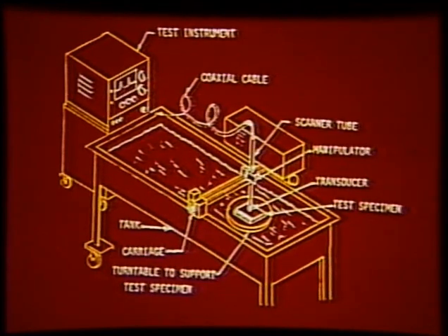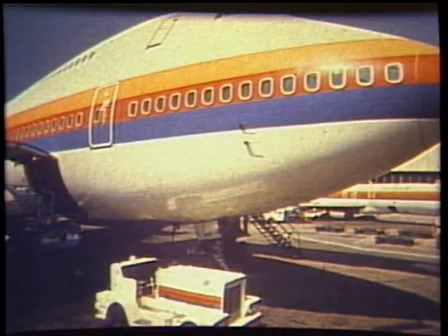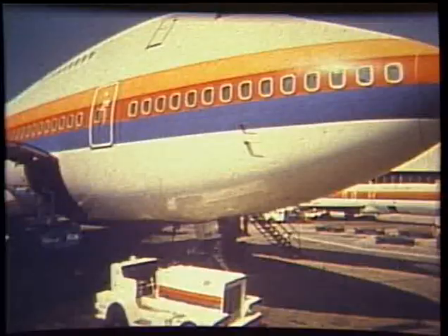Immersion testing is a variation of the contact method used quite often in the testing of larger components. The test is conducted with both transducer and part submerged in water. The water acts as the couplant and allows the signals to be transmitted into the part. It is recommended for testing complex components and is used extensively in the aircraft industry.